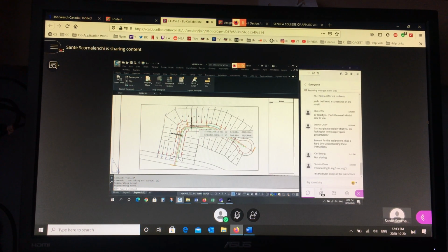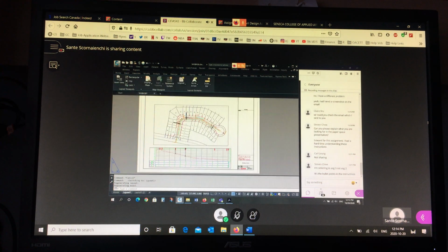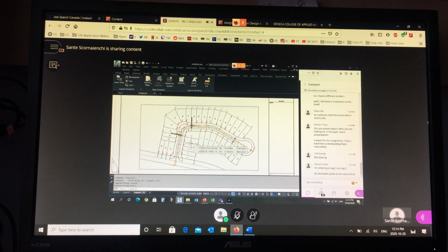You're doing all your design in one file, so all the information is in model space, but you don't want to see everything in model space in each drawing. So in paper space, when it comes to the plan profile, there should be nothing related to grading. So no point elevations, no contours. When you do a grading plan, it represents what's on the surface of the ground. So you shouldn't see anything underground. So no pipes. Maintenance holes, yes, but no pipes.